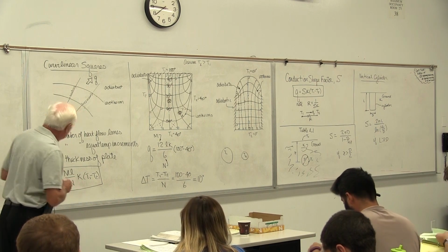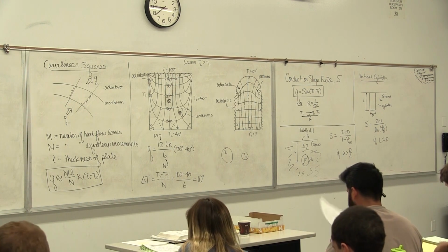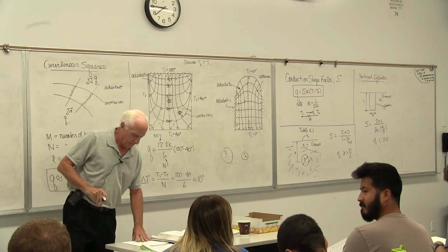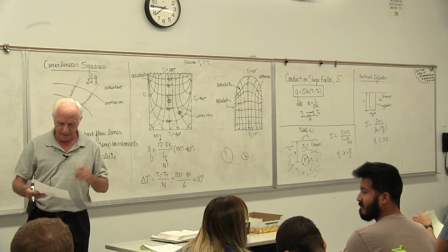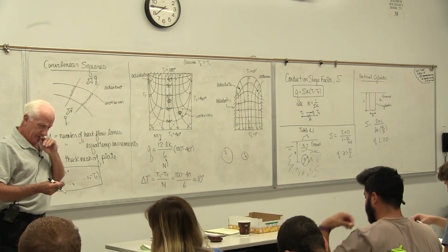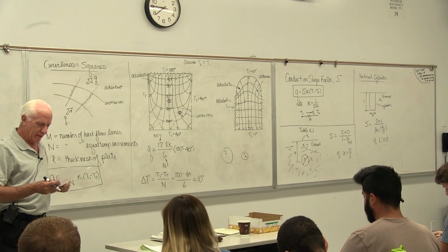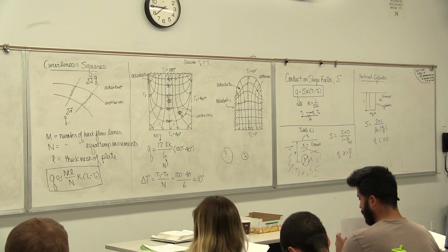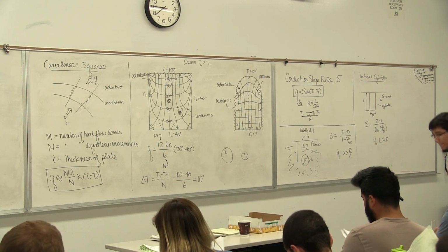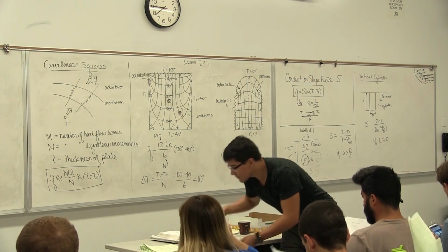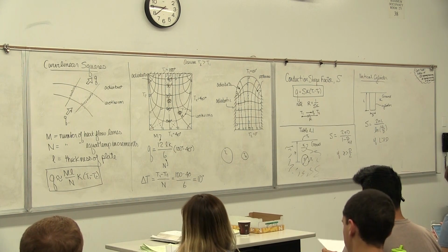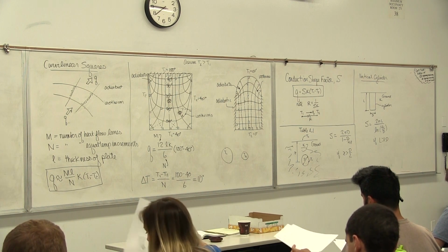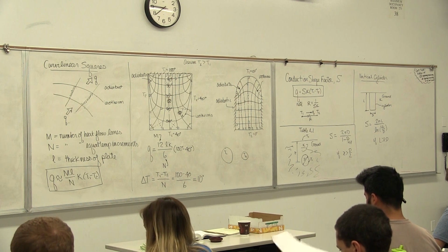Okay, let's talk about 3.15. 3.15 is the wall problem. It has a hardwood siding on a house. It has hardwood studs, gypsum layer, and insulation. So this is a hardwood siding. The K value was 0.094 from the appendix.